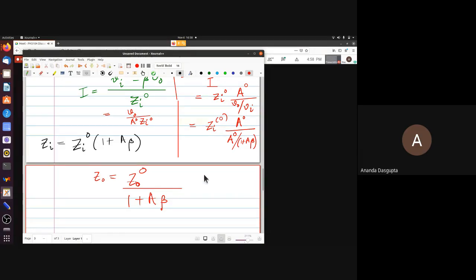But you should remember from whatever we studied about filters, that for circuits which have capacitors, etc., you may have a behavior like this, where for the amplifier, this is what you have. This is the subject of our next video anyway. You plotted the gain of the amplifier versus frequency, you will find a region. I've talked about that briefly in the video which has already been uploaded, but the details are in the next video. There's a region of frequencies which is called the mid-band frequency range, where the gain is independent of the frequency. If you go below that, the gain falls down. If you go above that, the gain falls down.